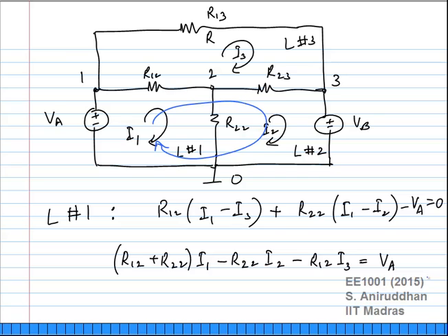Actually, there is no problem. I hope you realize this is mesh analysis. I can extend this to what is called loop analysis. There is nothing that prevents me. Is there anything that prevents me? KVL is always valid. When you start from one point and return to the same point, KVL is always valid. What prevents me from doing this for non-planar circuits? No, more equations is okay. That is not the issue.